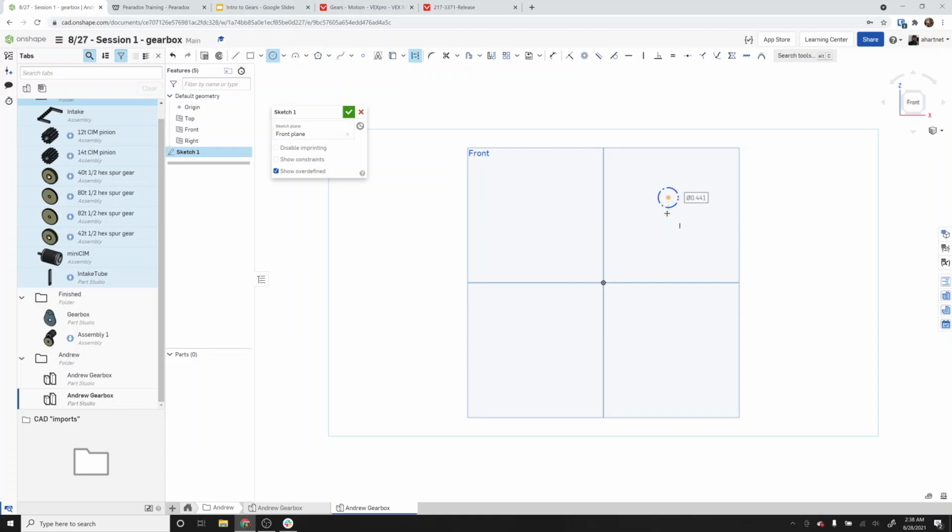We also want to make several other concentric circles. So you can see right now as I hover over this that it would be vertically in line with a circle above it. But really I want it to be coincident. Alternatively, you could do concentric. So if I wanted to, I could make a circle out here and make it be that 0.75 that I was talking about and use the concentric tool to make these circles be in line.